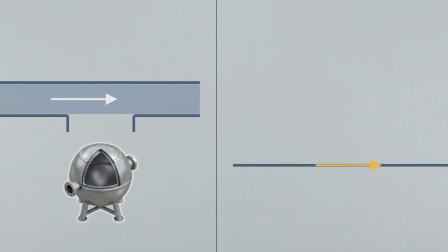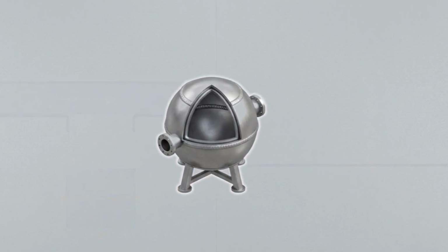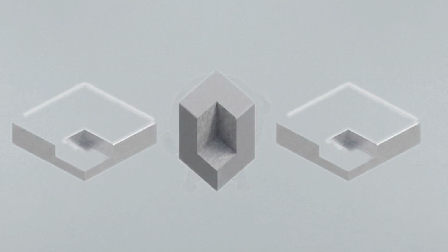To visualize this process dynamically, we can look at a hydraulic analog, comparing the flow of electrons through a trace to water flowing straight through a pipe. Inserting a capacitor into an electrical circuit acts exactly like adding an open buffer tank to the main fluid line. The tank gradually fills with water while the primary flow continues unabated. As the tank reaches capacity, the accumulated fluid pushes heavily against the internal walls, creating outward mechanical pressure. We map this mechanical pressure directly to electrical voltage.